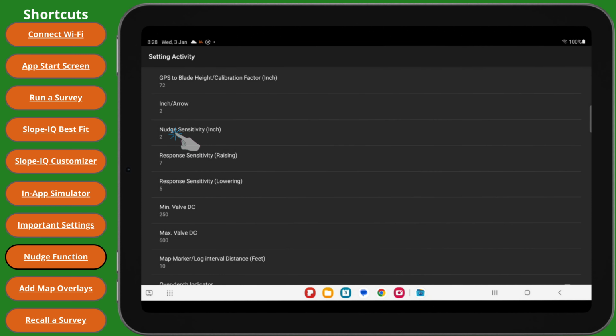You may also wish to adjust the nudge sensitivity value for the manual nudge function. This is related to the nudge up and nudge down buttons on the grading screen. Where a cut is too much for a single pass, the operator can nudge up one or more times to reduce the cut. Then, on subsequent passes, they nudge back down until the final grade is achieved. Remember, you also have the option of using auto nudge, which we'll cover as well.